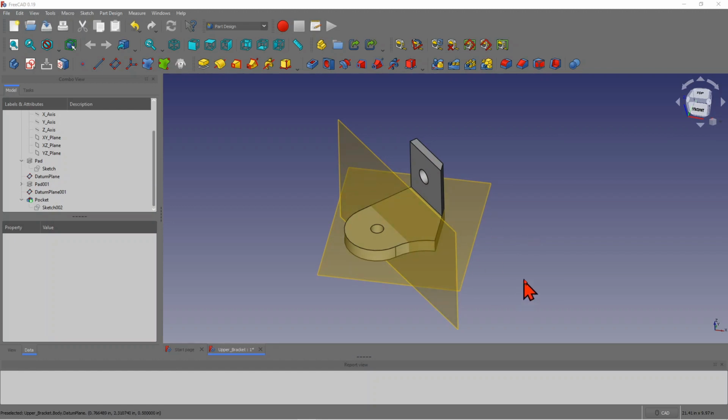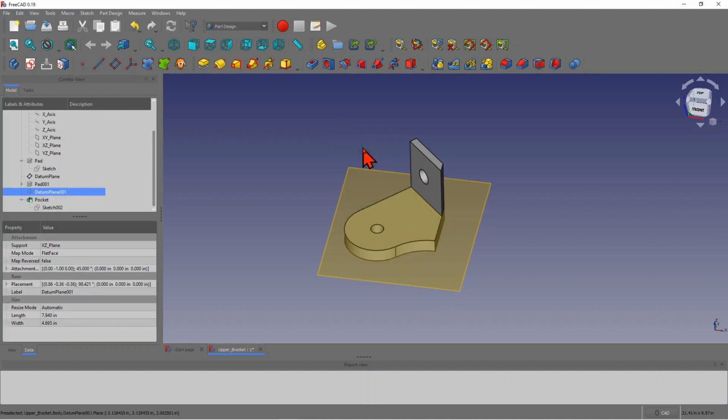So far so good. Okay, so now next step is, since we have created the symmetric portion of this model, we can mirror it. So we're going to use this icon here, this button here, to create the mirror image of this solid. Okay, so let's get this guy out of the way.